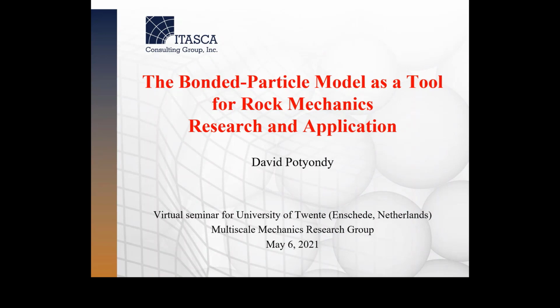But yes, rock mechanics is very much in the brittle realm, and oftentimes it's small amounts of strain, because you make a tunnel and you want to see whether the roof is going to start to crack or not. But relatively high strain rate, right? No, not necessarily at all. Most of the work that's done is quasi-static loading. Now, some people are using these models also for rock blasting, and there you're getting really high strain rate. Because this is a fully explicit dynamic model, it can be used for those types of things as well. Everything I'm showing you today has been quasi-statically loaded.